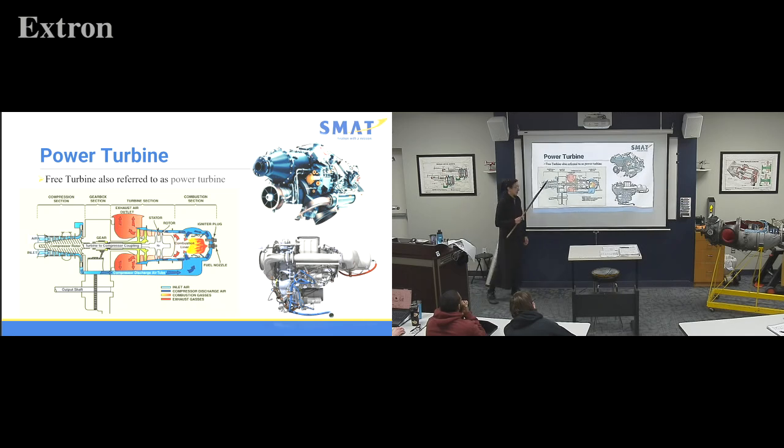What kind of compressors do we have in the Allison? Axial and centrifugal. If you look when you do your engines back through, you'll see centrifugal compressors. So both the PT6 and the Allison use axial flow and then centrifugal flow. Allison is pretty cool because they take compressor discharge air and pipe it the whole way to the back, so you have these big air tubes going the whole way back to our burner. Now air comes back here where our igniter and fuel nozzle are and goes into the combustion chamber. Then it goes out through our